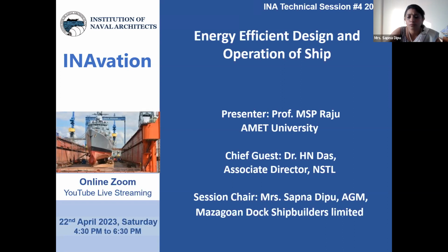Another thing is, people have to understand what EEDI is and what the actual CII is, and the underlying difference. That needs to be understood by everyone in our industry, because EEDI is a very ideal condition, when there is no wave, no wind, and an absolutely calm sea. But CII is the actual measure of the fuel consumption in actual sea conditions. So these two are quite different.